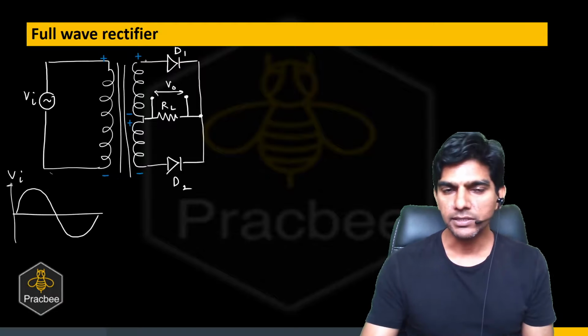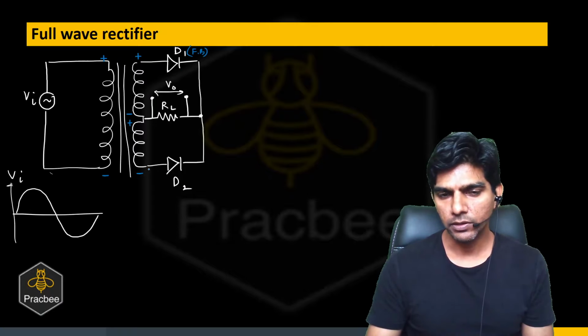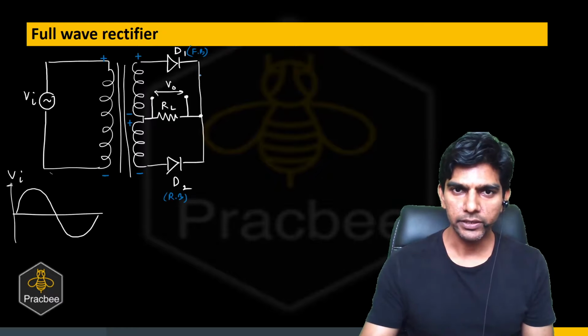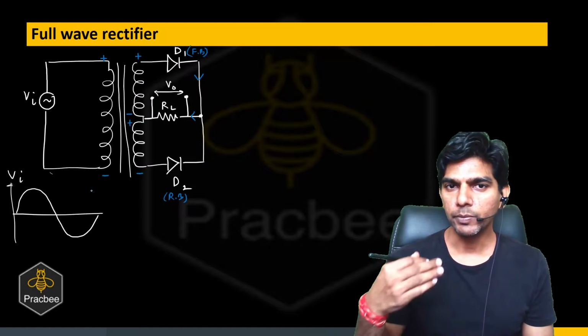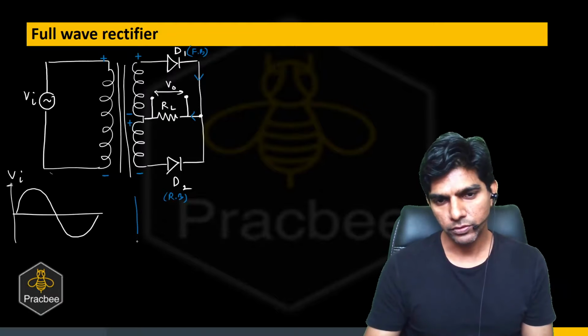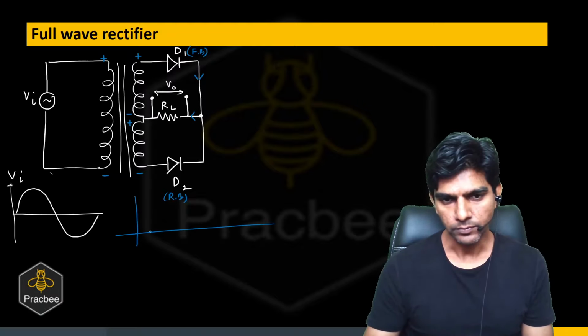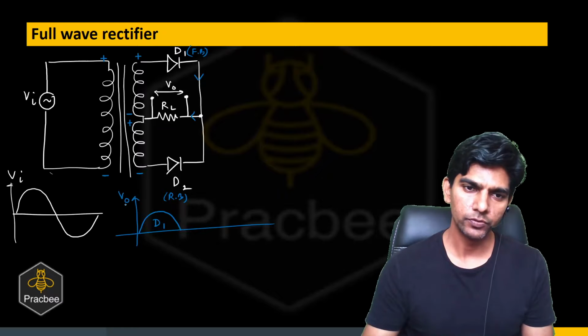So D1 is connected with a high potential, so we can say D1 is forward biased, and D2 is connected with the low potential, so D2 is reverse biased. So what is happening here? There will be a current through the resistor like this. So there is a current and we'll have some reading. So we will be able to rectify the first half wave. If I show it on the graph, we are able to rectify half wave, and this is because of the diode D1. This is the output voltage.